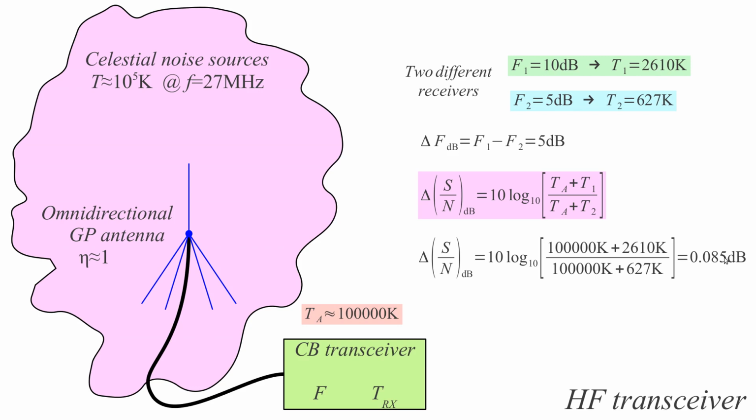It made no change in the final signal to noise ratio. So noise figure comes up only when microwaves come up. When microwave links, when cable communications over cables come up, then the noise figure makes sense, and then the receiver noise makes sense. And noise temperatures make sense. While at HF, because of the high noise temperature of the sky, the noise temperatures of the radios used make very little sense.